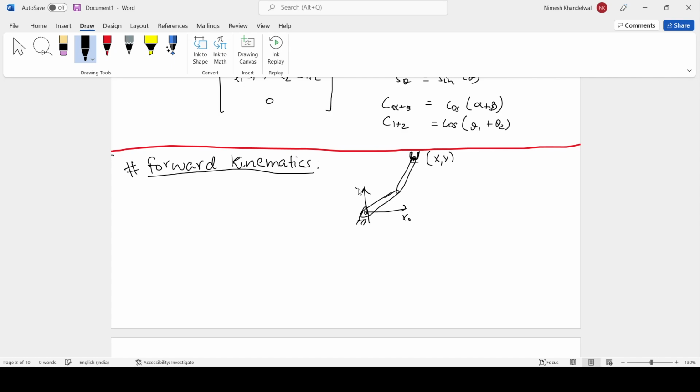This is your x0 and y0. But generally in robots you cannot directly control these coordinates of the end effector. What you can control is the relative angles, or the joint angles between any two links. How does it happen? Because all the different links are connected through motors.